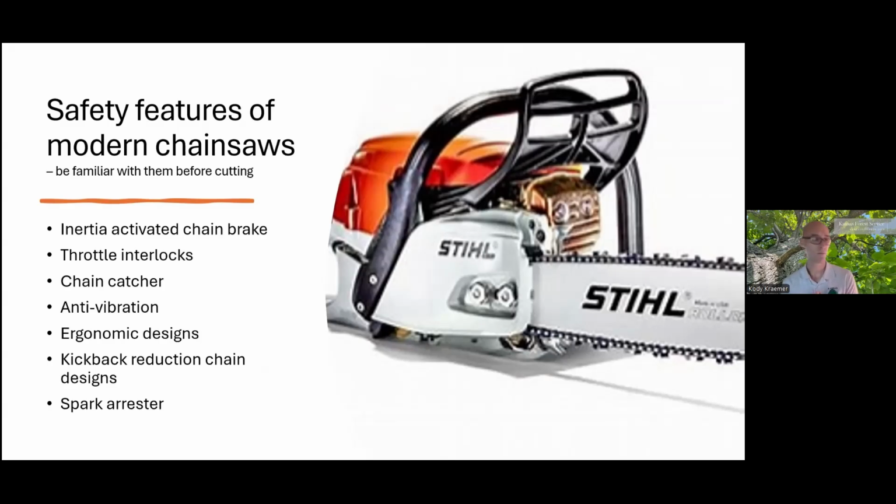Also, my one tip of chainsaw maintenance is take the time to sharpen or replace your chain. It will be well worth the time investment. Sharp chains are actually safer to use and more efficient than dull chains. So try to keep your chain sharp.